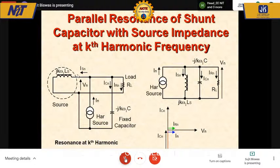That's a very difficult question to answer. You need to get some idea about the short circuit ratio of the source at your premises. That is the only thing that will give you a hint of the source reactance that is going to be present. That means with a hypothetical condition that you create a short circuit, what is the magnitude of current that will flow? Because under short circuit, the magnitude of current that will flow is limited only by the effective source reactance. So unless you get an estimate of that value, you really can't predict.